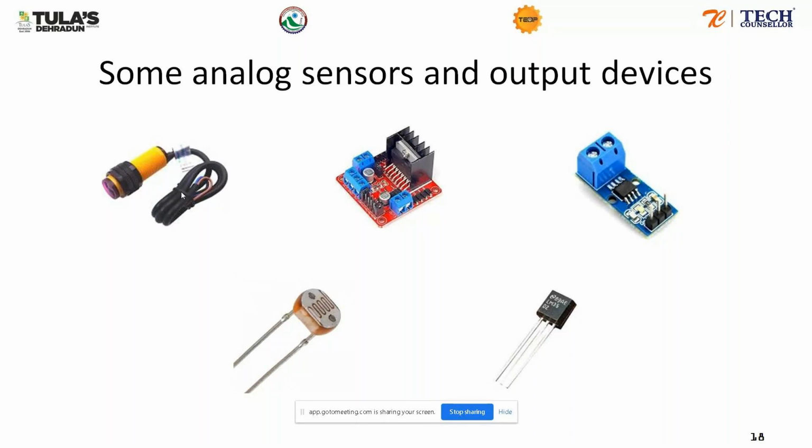If there is someone at a distance of, let's say, 2 centimeters, it will give you 5 volts. So in that way, we have to interpret the voltage coming from our proximity sensor, how much voltage it is returning. The more the voltage, the lesser is the distance. So that's how it works. For that, I'll show you all the codes and how to go about it.